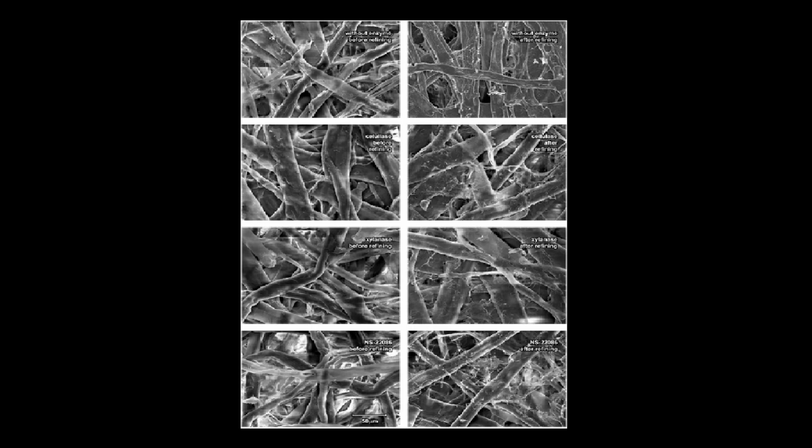Enzymatic modification of fibers aims to decrease energy consumption in the production of thermomechanical pulps and increase beatability of chemical pulps and improvement of fiber properties. In high-yield mechanical pulps, most of the lignin and hemicellulose remains in the pulps. Xylanases are applied to thermomechanical pulp, and when combined with an alkaline pretreatment, the amount of energy required for refining the thermomechanical pulp was decreased.